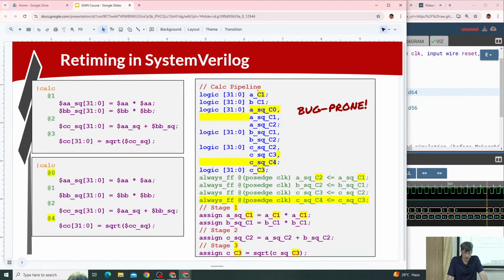Yeah, so this is the change in Verilog. Notably, we're following a naming convention here where the stage numbers are part of the signal names. As we stretch out this pipeline, we need to add flip-flops to support the extra pipe stages. We need to rename signals, so this assignment of CC changed from stage 3 to stage 4, so we're assigning it at a different stage, with a different signal name to reflect the pipe stage. Adding flip-flops here, so pretty torturous representation of several months of my life.